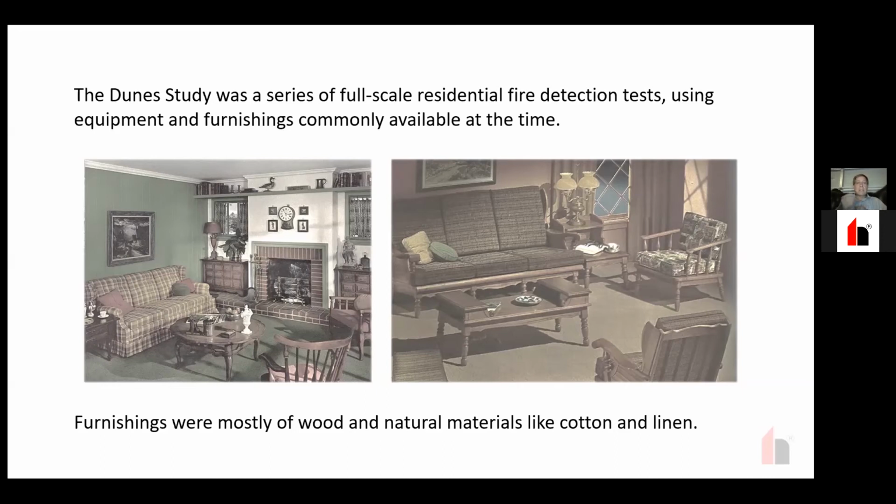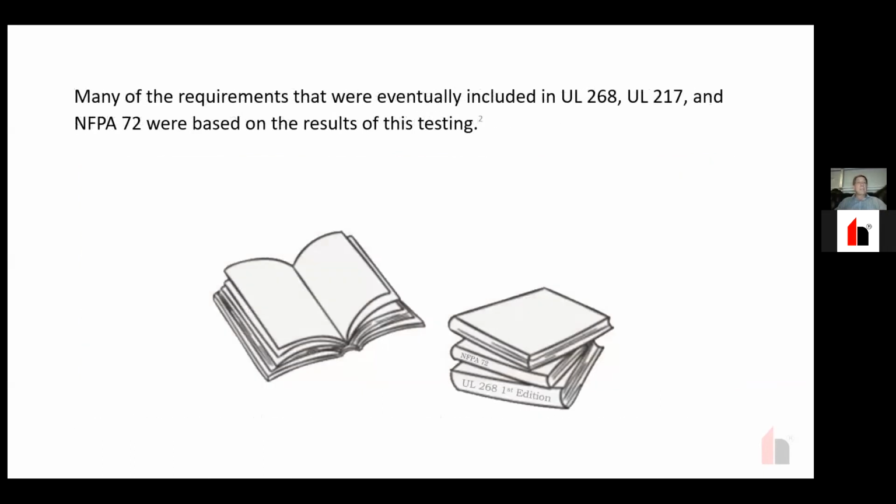And this study that they did produced a lot of valuable information about smoke detector performance, tenability time, and so forth. It produced a lot of good information that was eventually included in the UL 268, 217, and NFPA standards and codes. So this was very useful information.